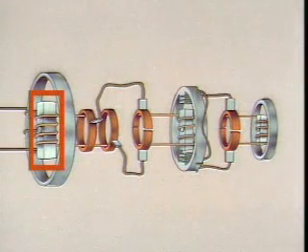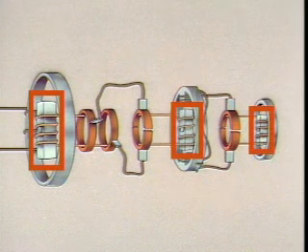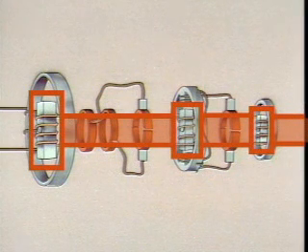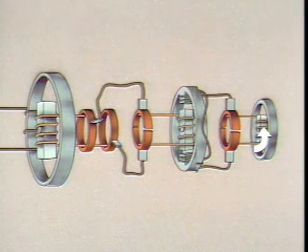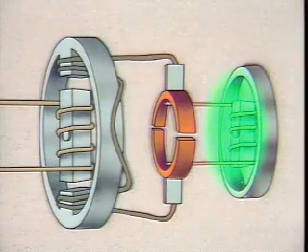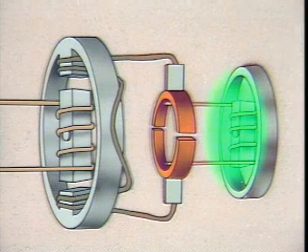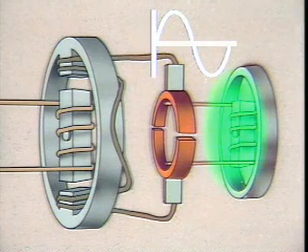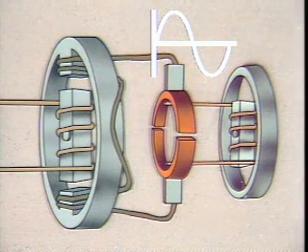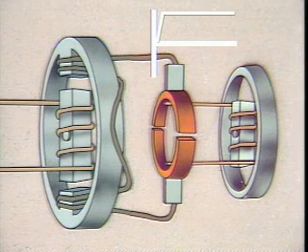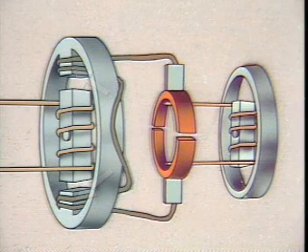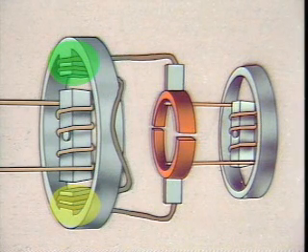The rotors for the generator, the DC exciter, and the pilot exciter are all turned by a common shaft that is rotated by a turbine. When the shaft turns the rotor of the pilot exciter, a small voltage is induced in the rotor windings. This voltage produces an alternating current at the pilot exciter commutator. The commutator converts the alternating current into direct current. The direct current flows through the stator windings of the DC exciter, creating a stronger magnetic field.